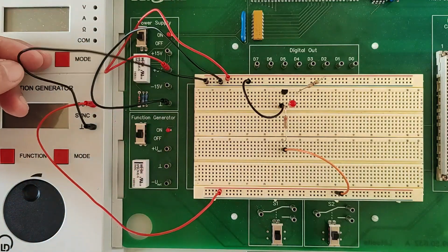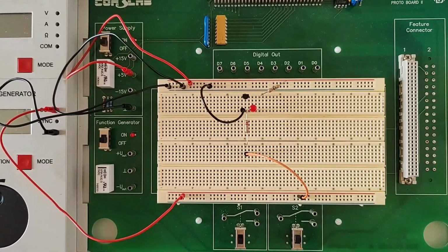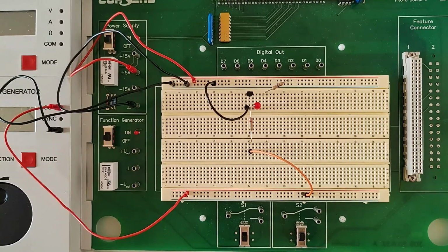There. Now, I could actually switch on the circuit right now because the circuit is complete. Now, what will happen if I switch on the circuit? Before I switch it on, I need to set first the function generator to output the square wave, and the frequency, I'll need to set it to 1 hertz, and also the voltage peak to peak, or the amplitude, needs to be set to 10.